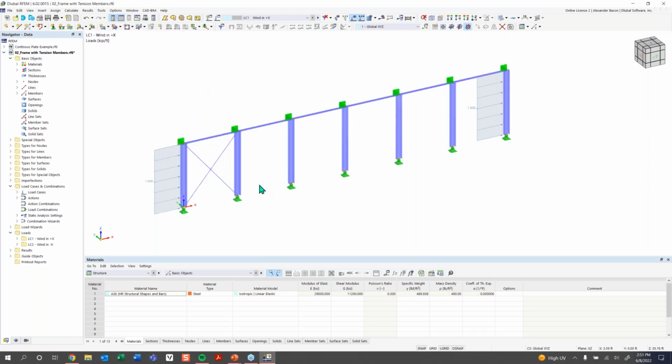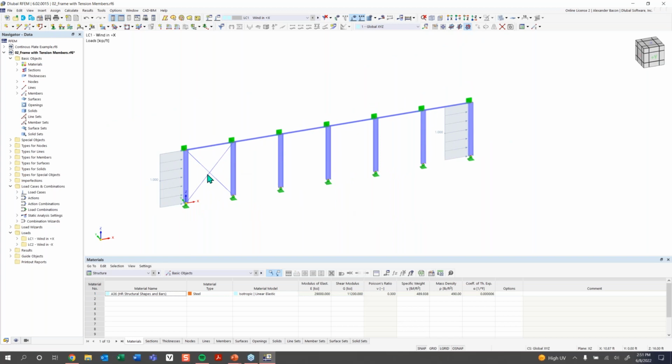I'm going to right click, and now I can simply take this X bracing that I've applied here, highlight it, hold Control to copy it. I can just take this, move it over while holding Control and copy it. It's supposed to copy, I need to keep holding Control, so let's do that again. Let go of Control. So now we have our copy there. And now we have our X bracing. So now this structure is braced in the X direction.